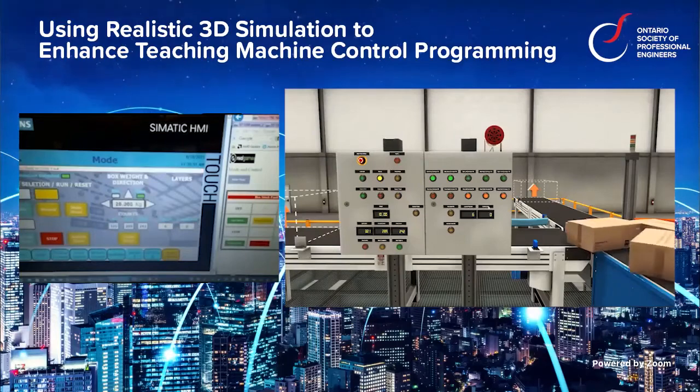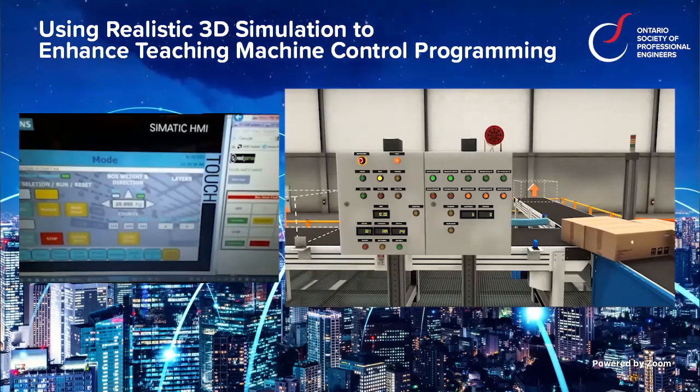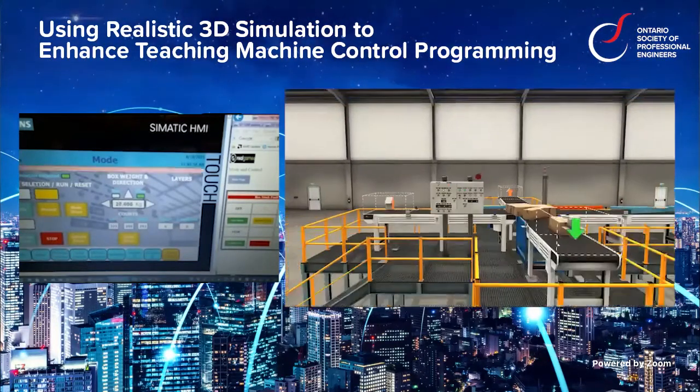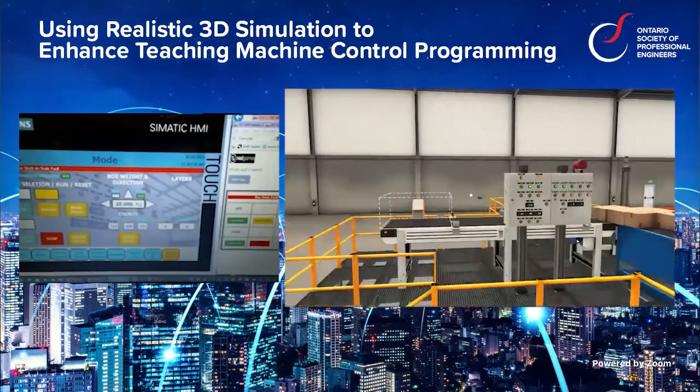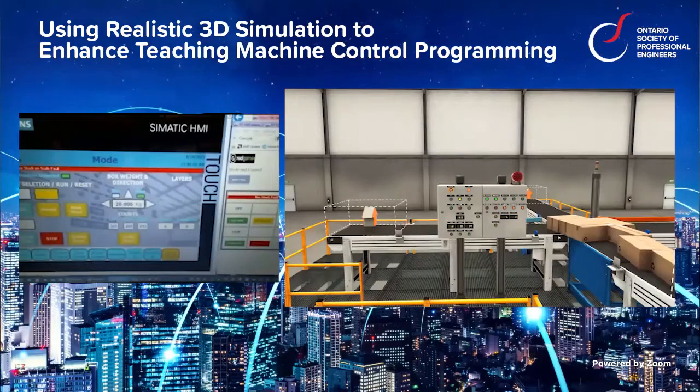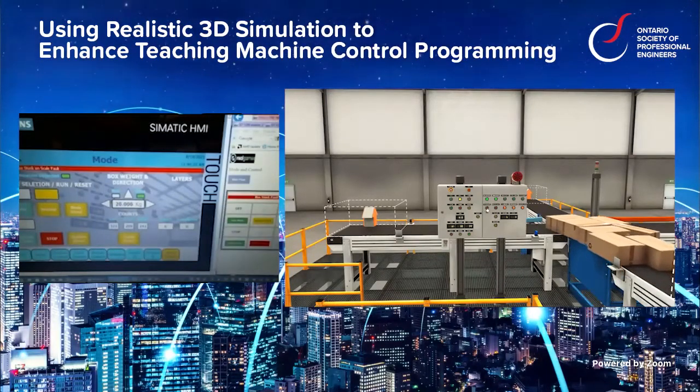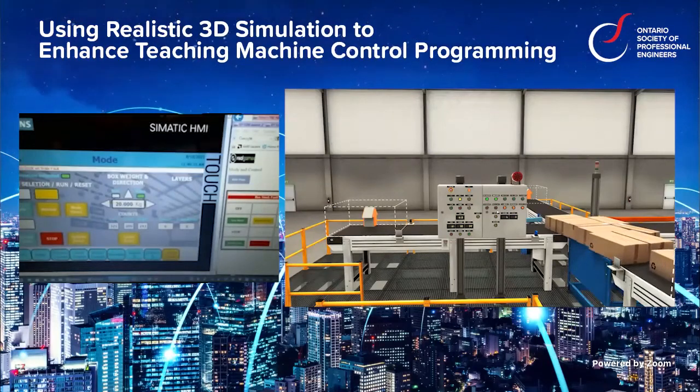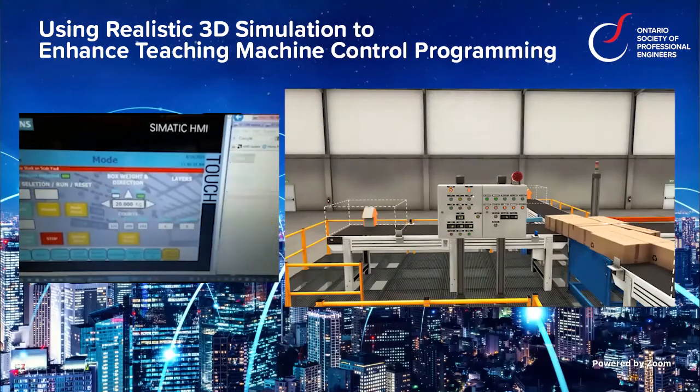I've already created a fault, which is the pallets or the boxes getting stuck in this area. So if an operator doesn't know what he's doing, he's now jammed up his equipment because he hasn't started it up properly. Manual mode should only be for exceptional circumstances. So now he's really messed things up, and unless he stops, say emergency stops, the system will just keep running and he's stuck. I'll do a system reset.